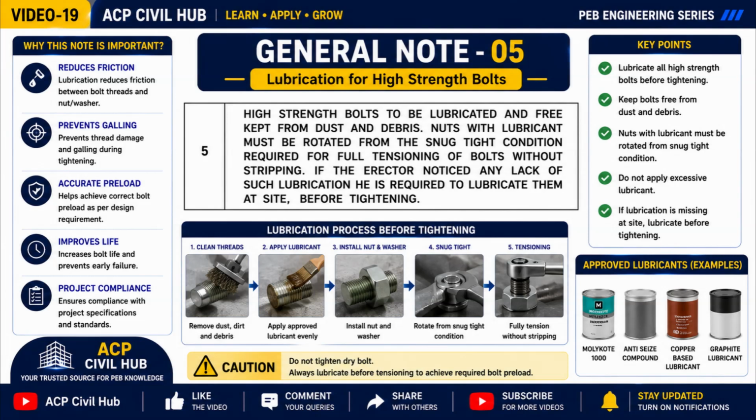Never tighten a dry or contaminated high-strength bolt because excessive friction can produce incorrect bolt tension, leading to unsafe structural connections. A small amount of proper lubrication can make a significant difference in achieving safe, reliable, and code-compliant bolt installation.